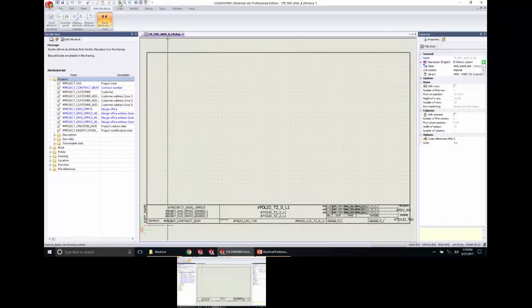Of course, up here at the top, notice how I let you guys know that as soon as you get a drawing open, these things become active and you can select them. So you can do zoom extents up there. You also see that Control E is the keyboard shortcut. But double middle mouse button is the same thing. I find it's a long way to go up there, especially when I'm in the thick of it.